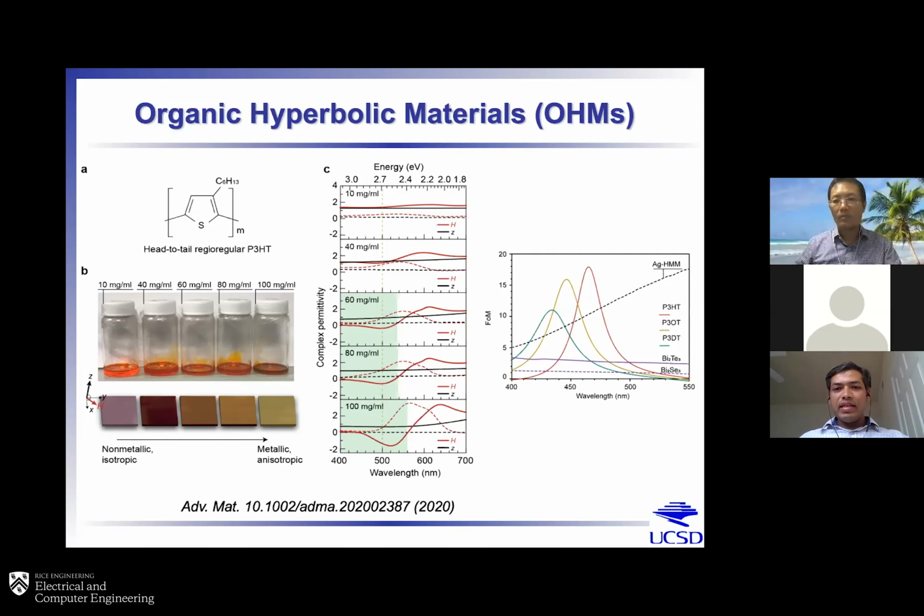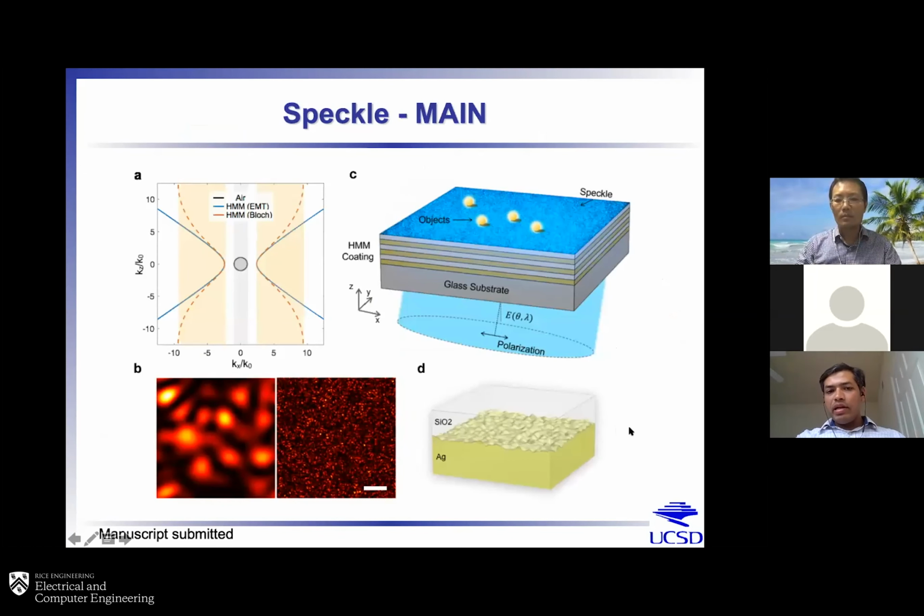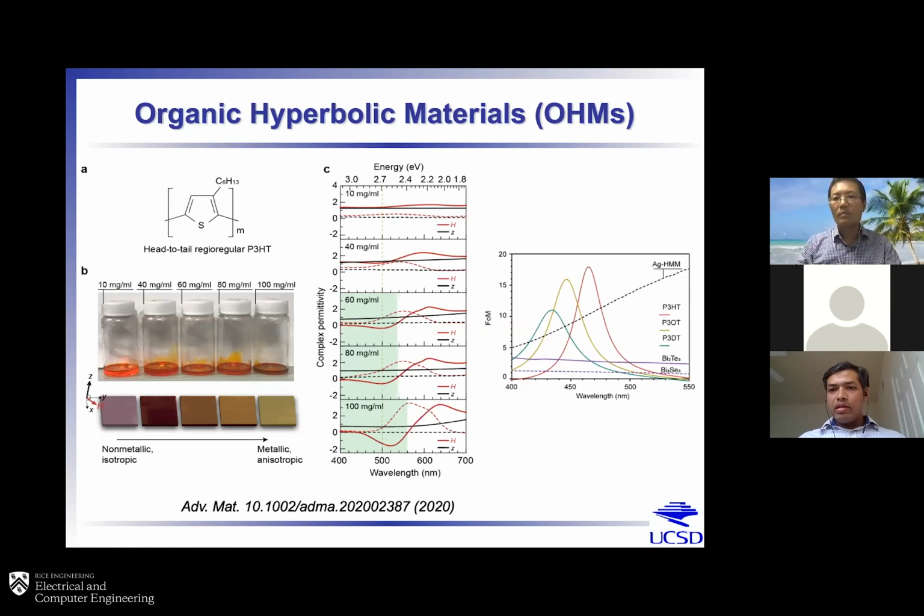Also, maybe just a question related to the light emission part. Clearly, the advantage you're getting in increasing the quantum efficiency with light emission is mainly because you're reducing the size, so you're causing the k-space points to be more quantized, and hence momentum matching is easier, right? Otherwise, the momentum mismatch of electrons is too high for them to be injected or even for the tunneling to happen. And that's what you're beating with quantization. Is that right? Which means you can probably do better if you shrink the quantization size or even add one more dimension of quantization.